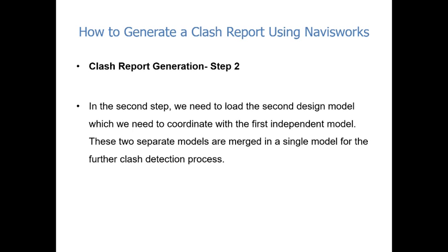One of the issues that happen during model appending is the origins, the shared coordinates. Sometimes the shared coordinates don't align. For example, the shared coordinates, which is the base, is 0, 0.